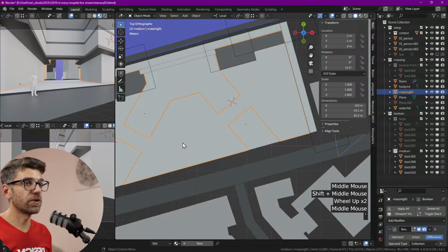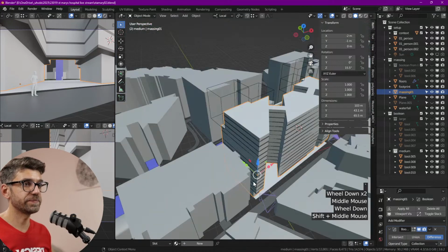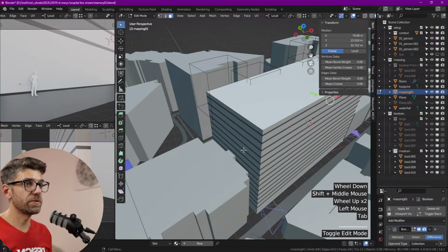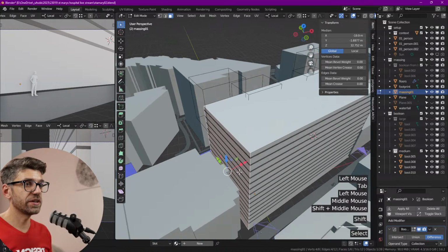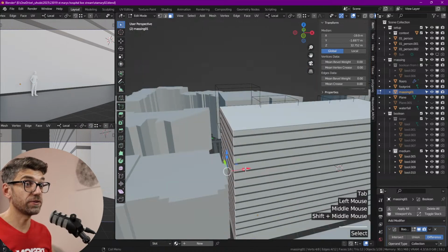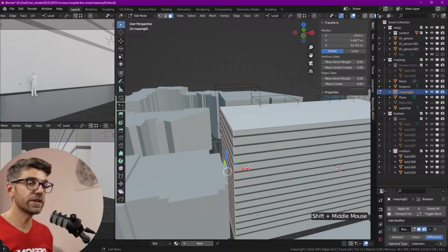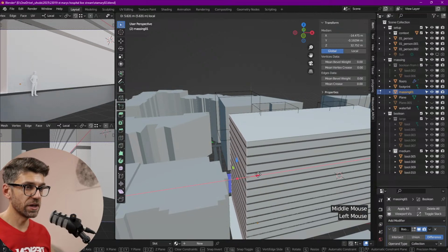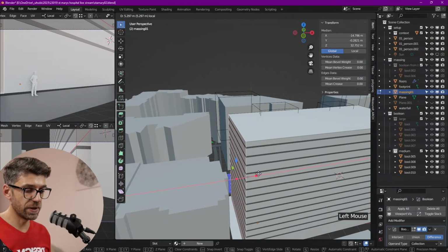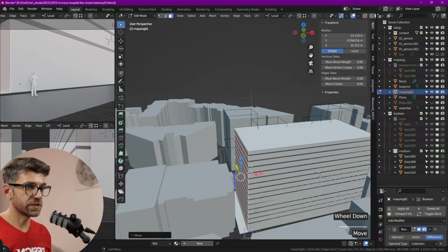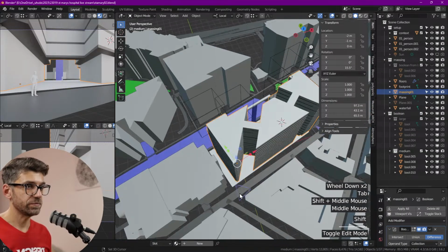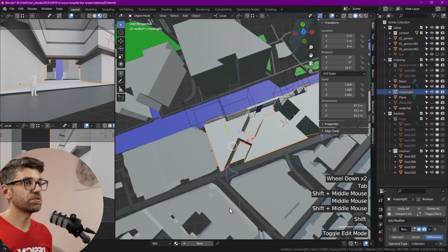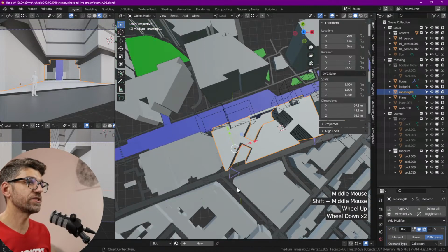Now let's go to top view on this side over here and go to the massing, select this edge, and we want to move it. Wow, we're literally touching that building. Again, footprint, not sure. These footprints come from OSM. To check that out, go watch the previous video to give you an idea of how it works. But I'm going to select this edge now and maybe move it back 6 meters.